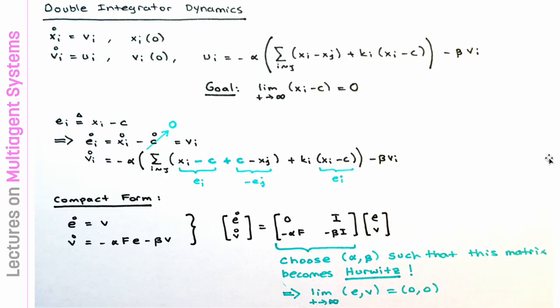Anyway, in the vehicle domain, when you deal with, for example, quadcopters, you can think of each quadcopter or aerial vehicle, fixed-wing airplane, each mode, like the pitch dynamics, roll dynamics, and yaw dynamics, as independent double integrator dynamics that are decoupled from each other.